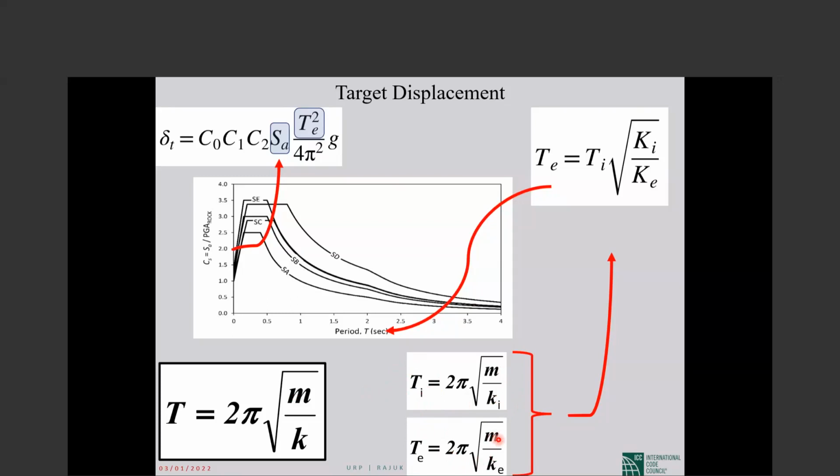You tell what is your definition of equivalent mass, equivalent stiffness. You define this. Then we divide these two together and reach this. So, for example, here we say, okay, during an earthquake, yes, mass changes. Some floors maybe, some of the mass falls, changes, but it's not that much. But mainly stiffness changes.